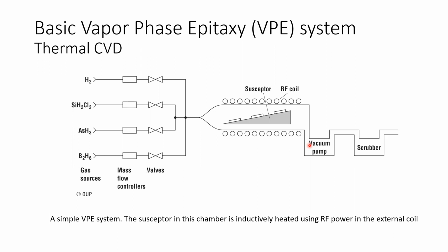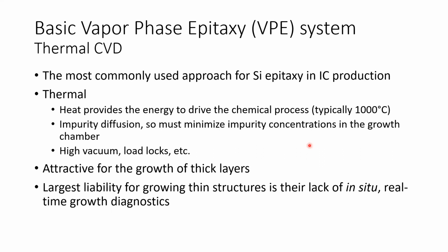So simply it is a thermal CVD, sometimes low pressure thermal CVD. This VPE is most commonly used in silicon epitaxy in IC fabrication.